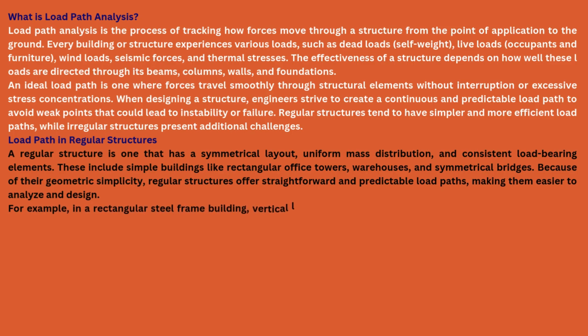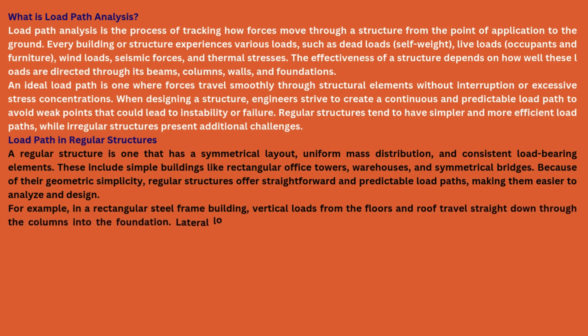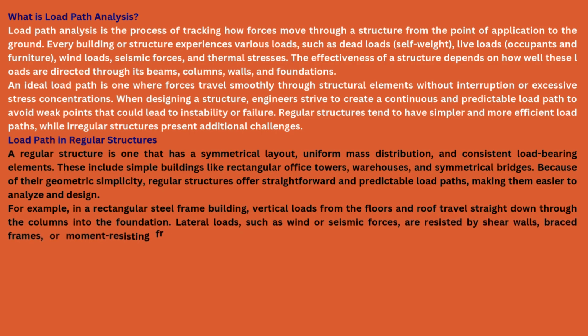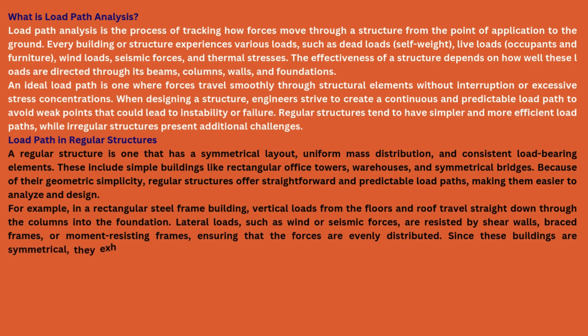For example, in a rectangular steel frame building, vertical loads from the floors and roof travel straight down through the columns into the foundation. Lateral loads, such as wind or seismic forces, are resisted by shear walls, braced frames, or moment-resisting frames, ensuring that the forces are evenly distributed.